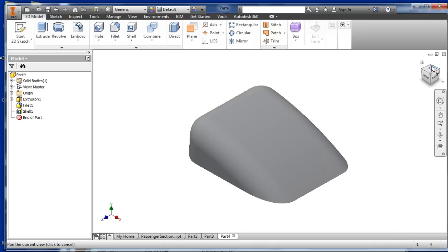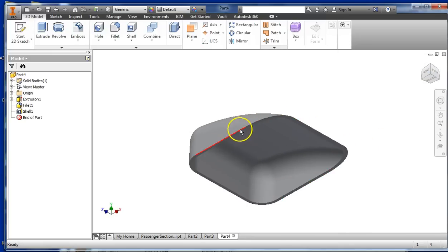Next up, as I'm in, really I guess it's part 5 and number 3, we're going to create the interior wall structures that come out from underneath this, and that's what actually sticks into the wooden block. Okay, we're going to use an offset work plane. If you look at your multi-view drawing, you can see that that extends below the plane that would be defined by this lip, this flat surface here that goes around the bottom. Our walls are going to extend beyond that. So we're going to create a work plane that we can begin drawing on where that ends.